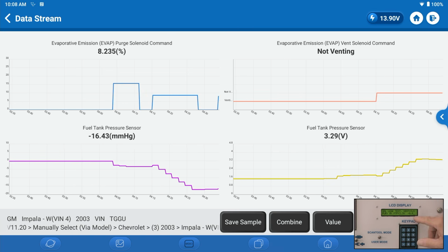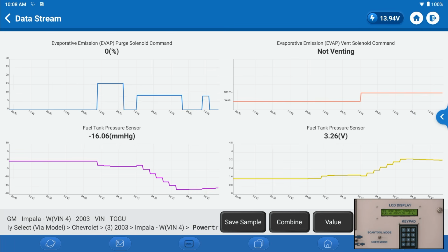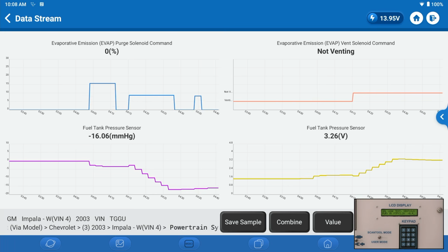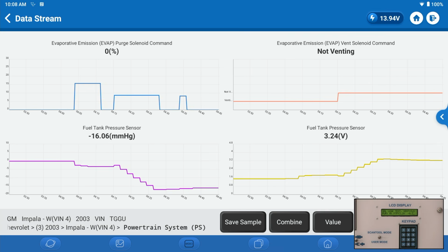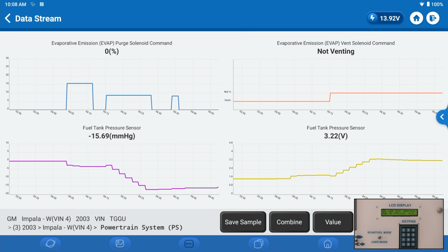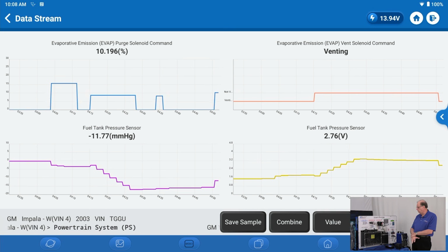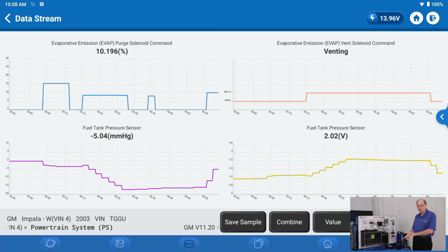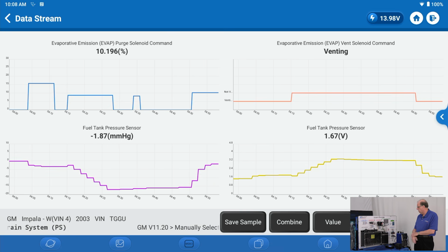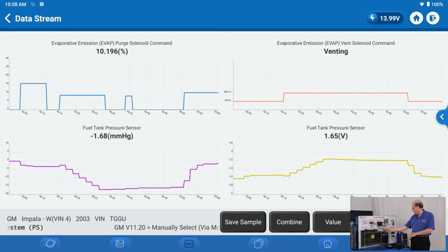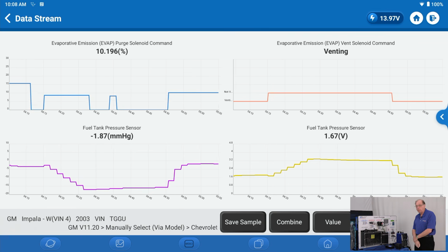And if you notice, we're down about minus 8.6 on this, 8.4. We're looking at the system. Fuel tank pressure is 3.2. And we'll have the scan tool hooked up so you can watch this also at the same time. Now we're doing a vent restriction. Remember I told you about if we get a vent restriction, it would cause problems with the system. So now they're checking the vent restriction on it, which would be over here. And if I just press on here, close it down a little bit, see the pressure, there was a little restriction there when I pressed on it.